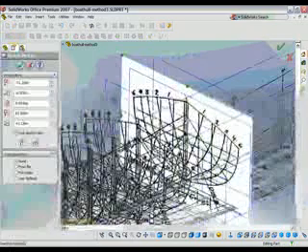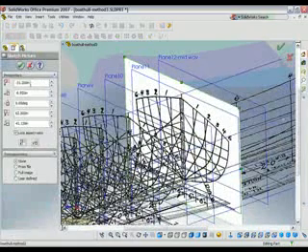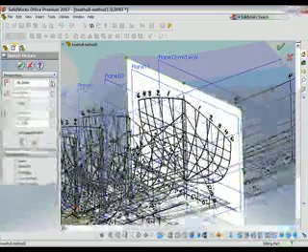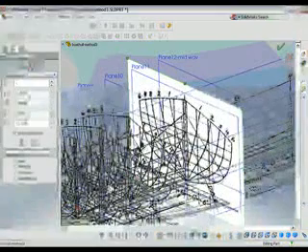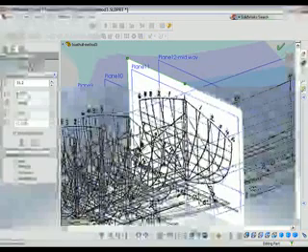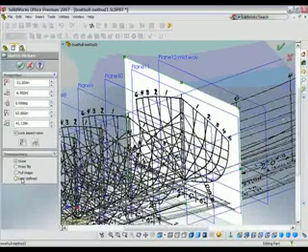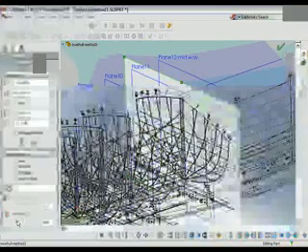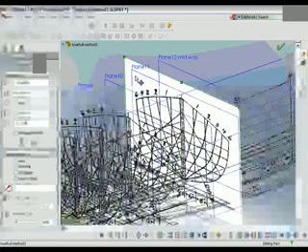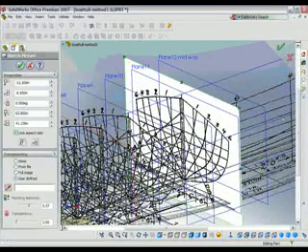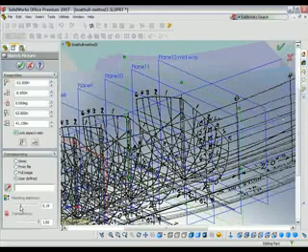Let's turn off the transparency. You see that there's drag handles that we can drag those around with, but also we can input numerically the X, Y, rotate, and scale values. Since each of these is identical, I know these numbers and I entered them for all of them. With the transparency, I assigned a user transparency of the white surround and then used that white as the part of the sketch I wanted to show transparent.